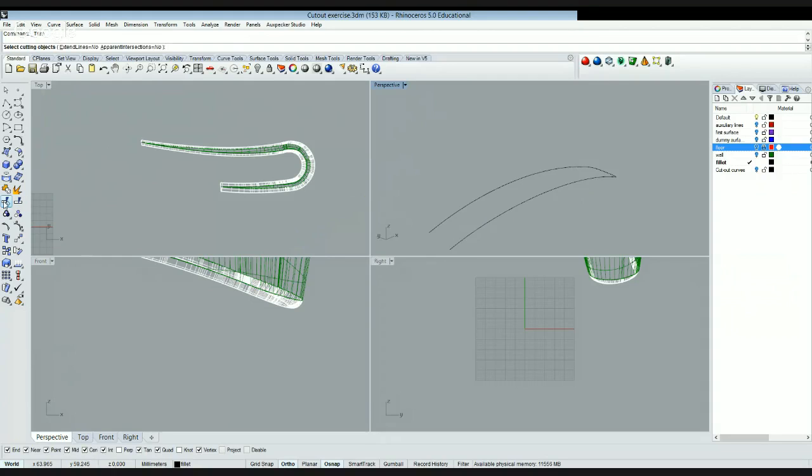Okay, I want to trim cutting objects. I'm gonna do something different. I'm gonna create a line here. And I'm going to trim along this line here. Okay. So now I have these two lines and hopefully I can join them now. Okay. It was an overlapping of two lines. So now I have my continuous joined line.